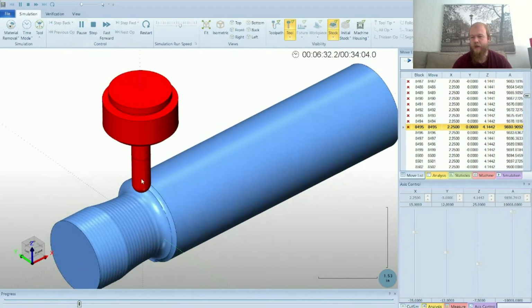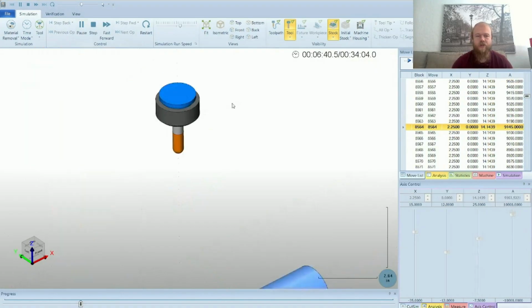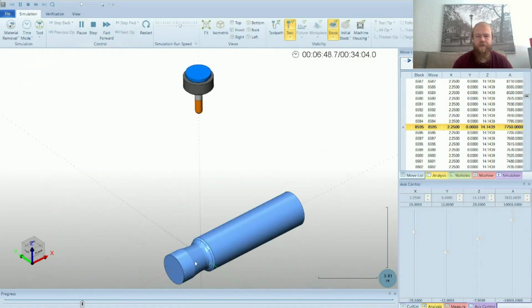You'll see it stop. The tool retracts up. The part is rotating the opposite direction now. So it's doing a rewind. And you can see it going from positive to 0. Then it's going to rewind all the way back to minus 9,000. So that we have all of that extra travel in the A axis once it comes back down and does the rest of the milling.